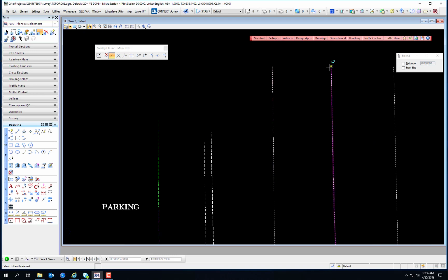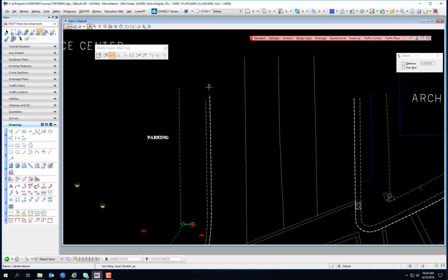So the first thing let's do is use the Extend Line tool and extend this line, and because we don't have to do an axis lock because it's essentially locked into the axis of the line, let's just snap to the top of the tallest pavement line just to make sure that all these pavement lines are the same length. And let's extend this asphalt line up to here and up to here. And just go ahead and grab all of these lines and extend them.